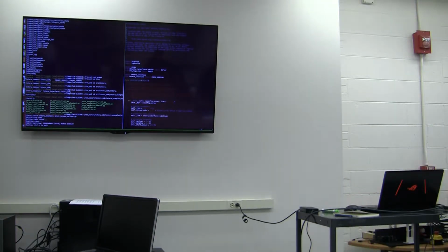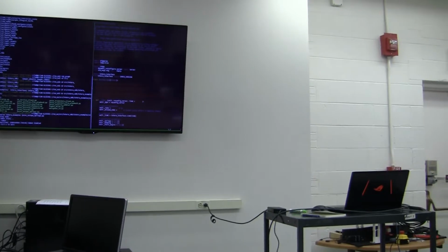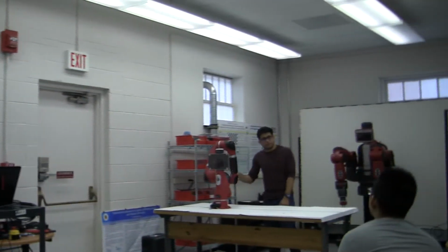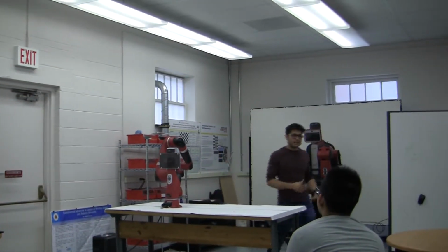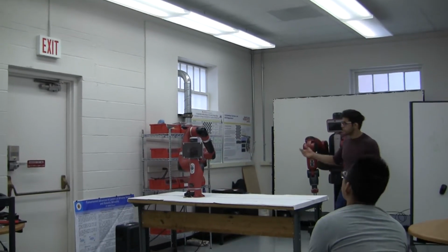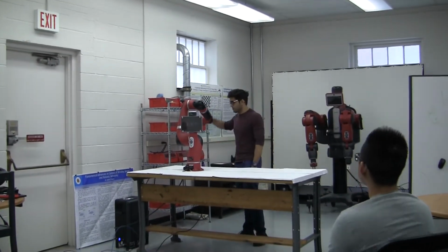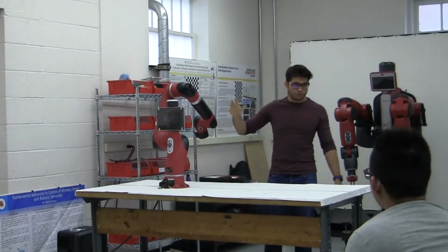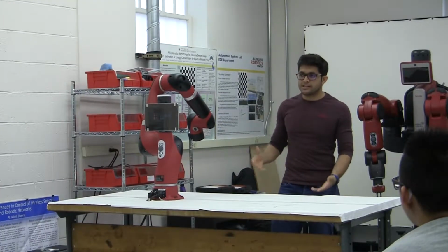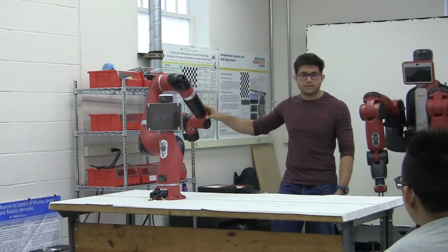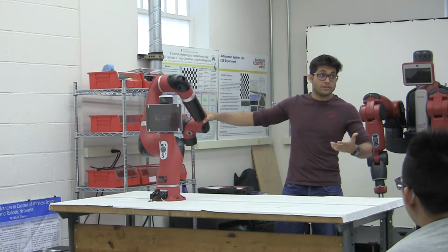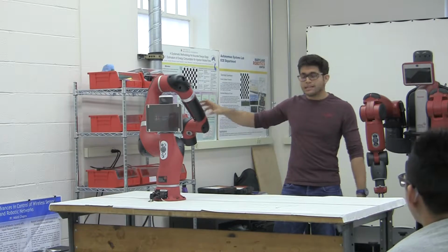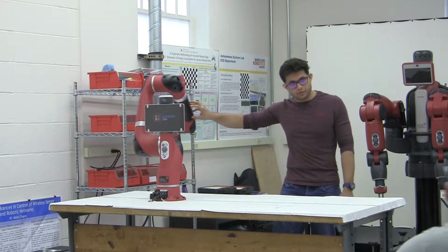Basically this runs a particular Python script which is like a spring command. It creates a damping function on Sawyer and a pseudo spring configuration, so each joint acts like a spring. It tries to go back to its initial configuration and you can move it with your force. All the joints in Sawyer are force related, and they measure the changes in position that you try to give.